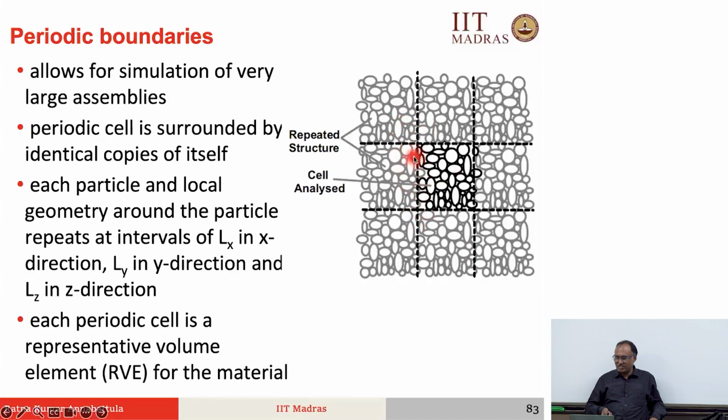When I say periodic boundary condition, if you have a particle here, when the particle leaves the domain, it does not leave the domain completely. It leaves from this end but exactly enters from this side. So the boundaries are not actually there, it is an infinite boundary. This allows us to simulate systems that are extremely large. However, this does not allow us to simulate the effect of the presence of a wall, because when there is a wall, the particle gets stuck there. But here the particle exits this periodic wall and enters from this side. Similarly, if it exits from this side, it will enter from this side. But this is very useful when you are dealing with very large scale systems.